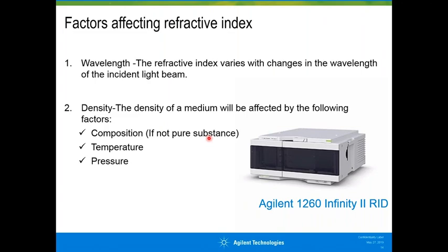Temperature changes would also affect the sensitivity of the detector, and might even give invariable spikes. Now, older systems were often used with a water bath for this purpose, but newer systems, all the latest systems now available in the market, have an option to control this temperature with a Peltier heater. So a Peltier temperature control is available.